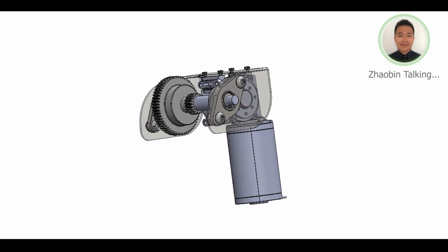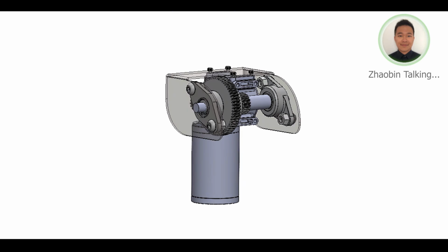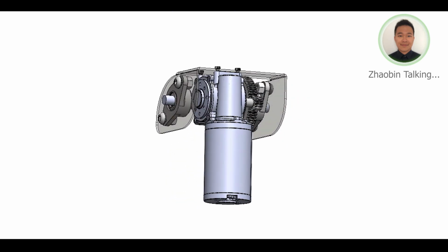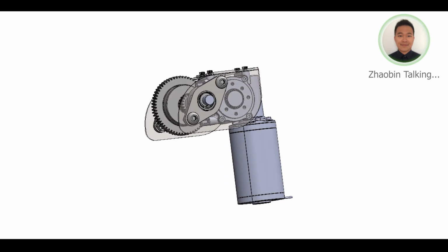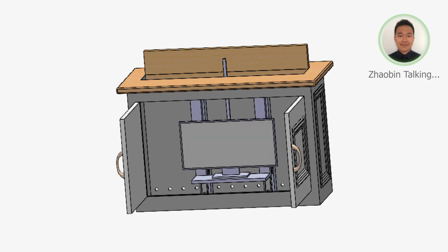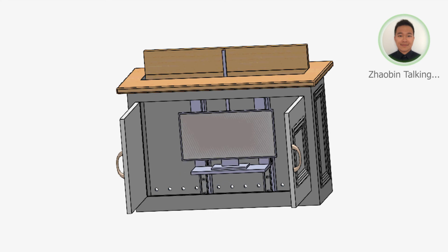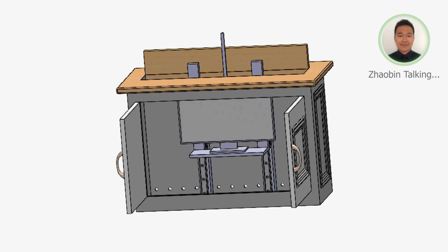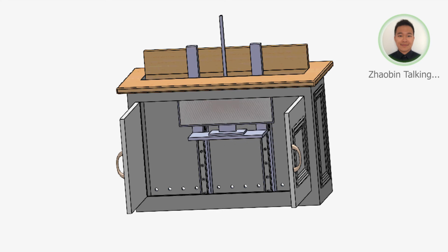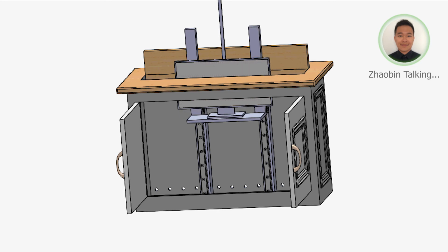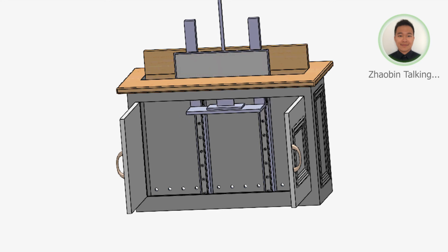And to have high stability, the TV lifter system we have is attached to two rails that are also attached to the protruding section of the back wall of the cabinet. We want to keep high stability. We also design our system with a factor of safety of 2 to avoid any disastrous failure or just in general prevent the TV from tipping over because of an earthquake or any sort of vibration.